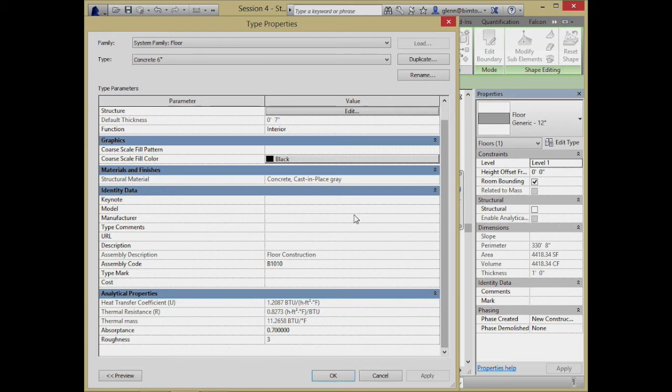So the good and the bad of this whole strategy is if the house gets really cold, the floor is going to get really cold, and it takes quite a while to heat up. So even if the heat comes on in the morning, it takes a while for the floor to catch up with you. On the other hand, if the heat's on throughout the day and you stop heating, the floor will re-radiate that through. Some people like that and some don't in terms of thermal performance. So just watch out for that.